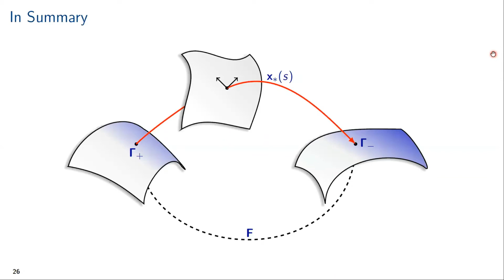So let me end with a brief summary of this approach and how both the planning and control tie nicely together. We have been looking, as a first step, to find some trajectories, starting with an initial state, and find some evolution of the state using the control input, which is consistent with the dynamics and path constraints and so forth, especially the dynamic constraint due to the underactuation, such that we evolve to some final desired pose, and then the impact mapping takes us back to where we started.